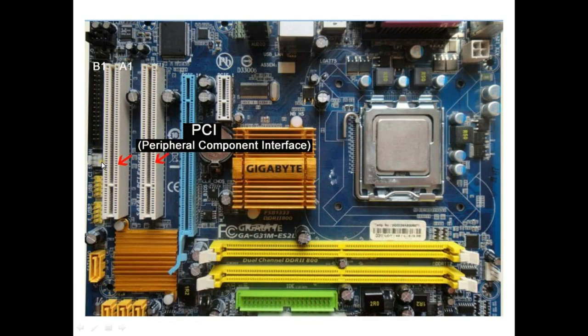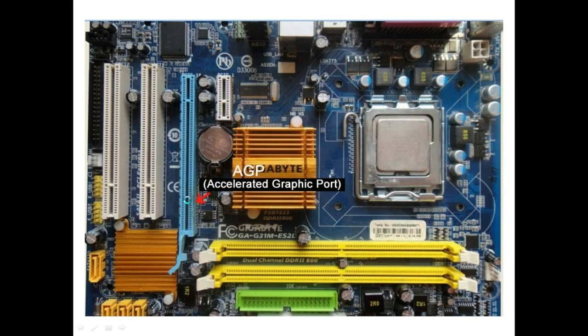And these two white color slots we call as PCI slots, peripheral component interface. There are two lines over here, one we call A, another one B. The pin counting has to start from here. These are used to connect the peripheral components. And this we call as a PCI Express slot. PCI Express communication is faster than PCI. And this port we call as AGP. AGP stands for Accelerated Graphic Port. It holds the graphic cards.